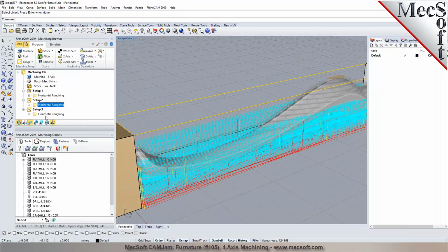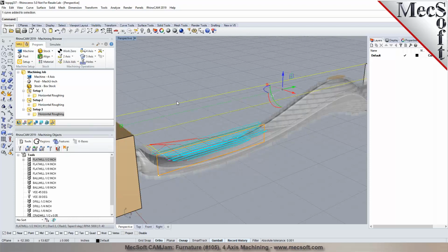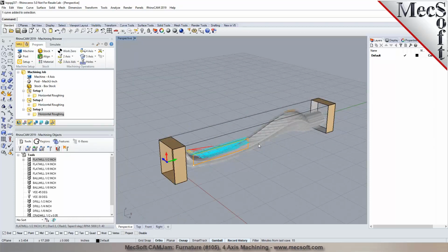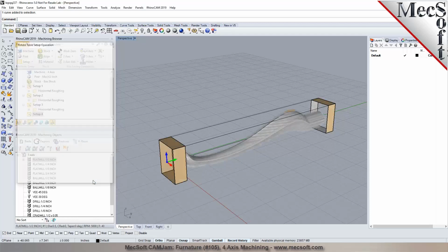Okay. So the expert offers you the following methods: roughing, parallel finishing, horizontal finishing, radial, and spiral machining in 3 axis. Now, these can also be used as index machining for 4 axis, like what you're looking at right here. Now I'm going to go back and rotate it to 0 again. So I bring it to the initial position.